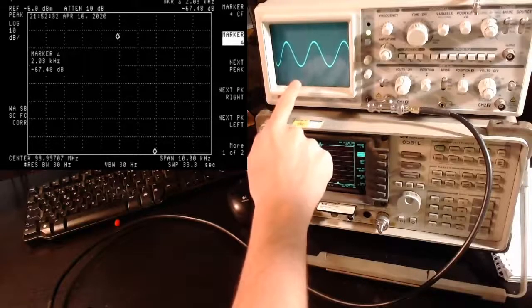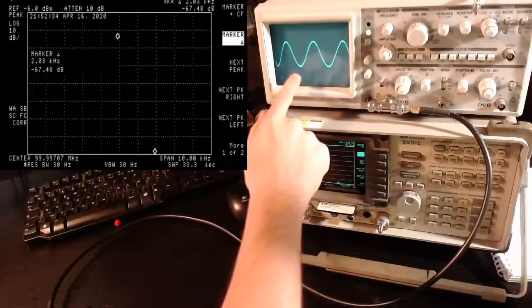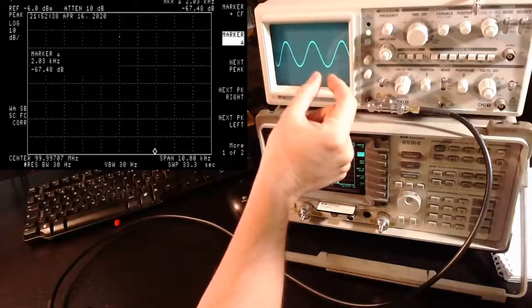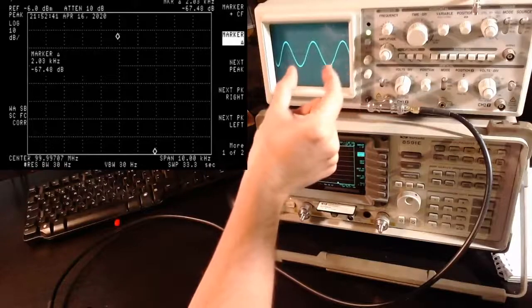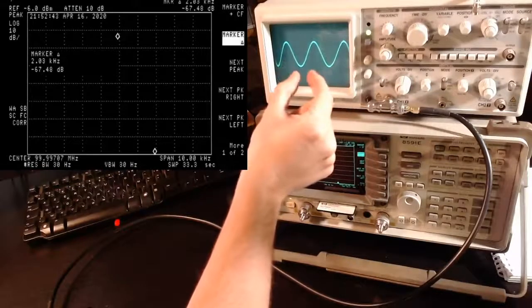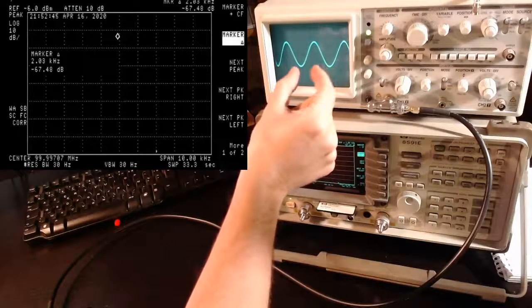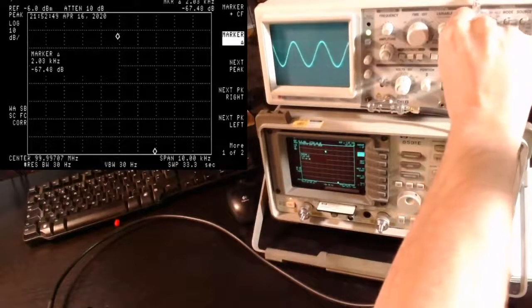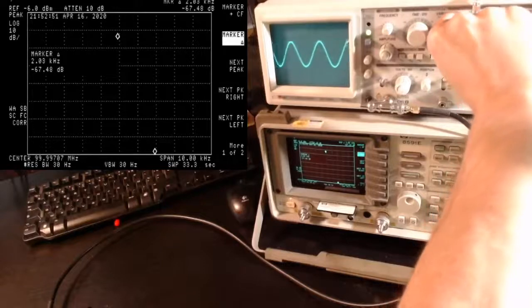So now the signal is being modulated in FM. The carrier is 5 megahertz, and the signal being modulated is a 1 hertz sinusoidal. So you see the frequency is changing every second. So this is the effect that is now displayed in the oscilloscope. If we change the position just to see where the signal begins, where it's being triggered.